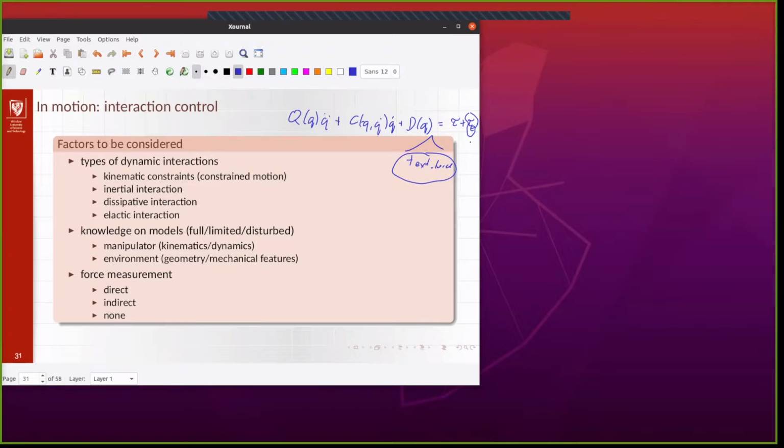And when you measure these additional torques that you are adding, you can evaluate what force was applied. So it's like indirect measurement resulting from the stabilization, from the additional torques in the motors that you needed to add. You just get the information, and transforming it to the external task space, you get the value of the force.